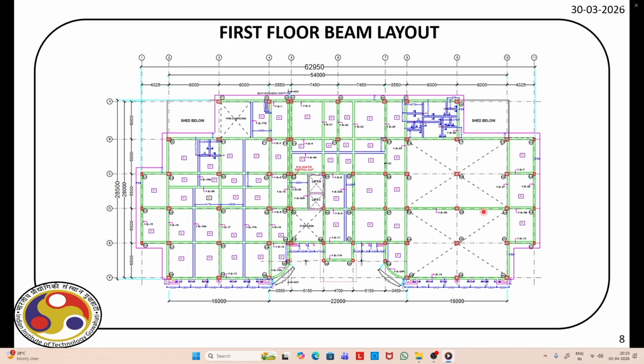As you can see here, we have an opening space for the lab with double height. At the respective level we will apply the floor load, and as I said, we will model these tertiary beams. For that we will make an approximation here. We will not make a very detailed model, but at this grid point we will have two tertiary beams.